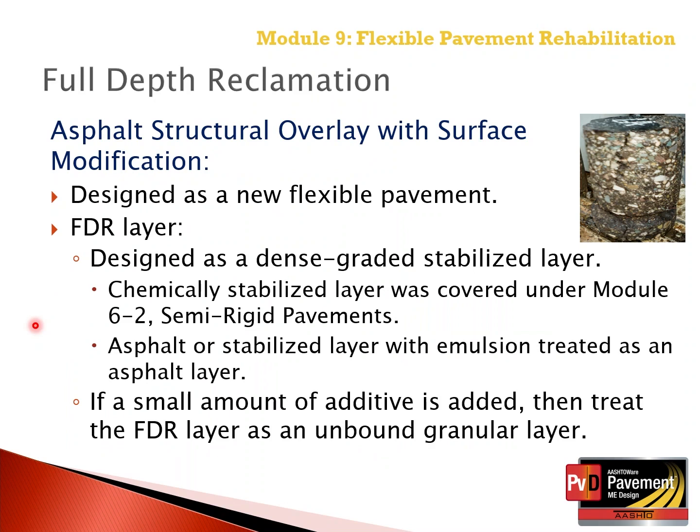Full depth reclamation. For full depth reclamation, that's where we're recycling the existing asphalt layer with portions of the aggregate base or underlying structure.